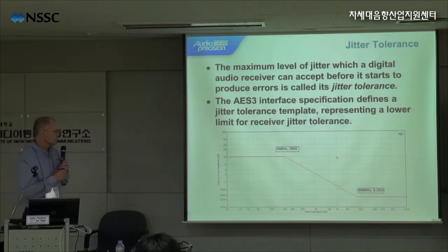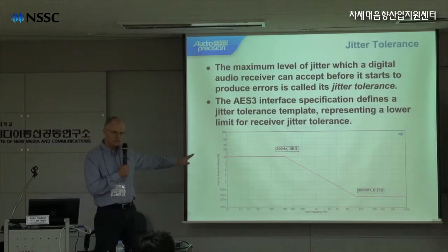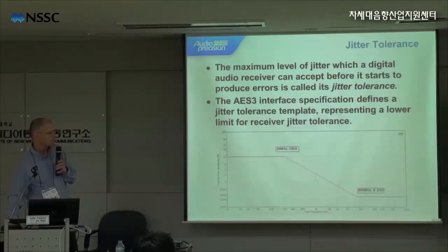So in the AES-3 jitter test, you would generate this level of jitter at different frequencies and check to see that the device does not lose lock or produce any errors.